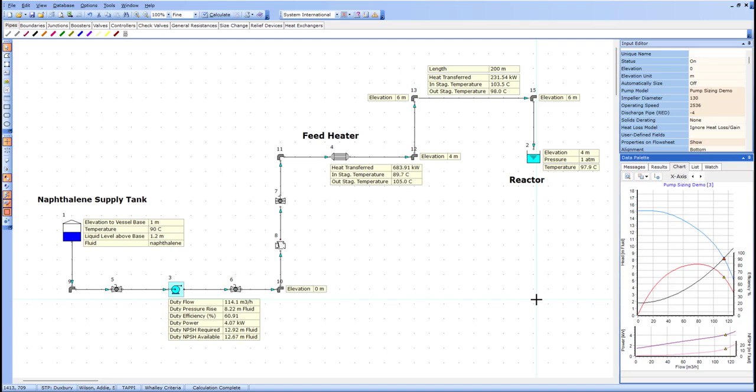For molten naphthalene, the impact goes beyond hydraulics. A larger pipe also holds more fluid and has more surface area, increasing heat loss and the risk of solidification during low flow or stagnant conditions. Oversizing compromises both pump performance and thermal performance.